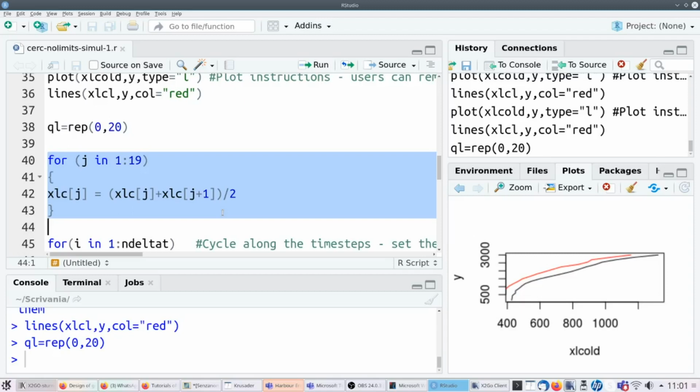Smoothing means that I want to eliminate singularities, which may be given by uncertainty in the data or by sudden changes of the coastline orientation, which are very local. I don't want to take into account the very local geometry, because sediment transport depends on the macroscopic behavior of the beach. I don't have to look at the very specific behavior in a given 150 meters spatial step. I need to look at the shape of the coastline over a larger spatial scale.